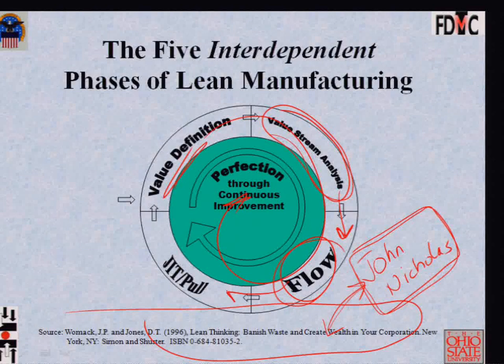After you have eliminated the flow related problems inside the value stream, then you institute pull production. You only produce to demand, and you check very carefully that you are not overproducing certain products, and you try to share your capacity, especially on the bottlenecks across multiple products, by reducing changeover times. And so there are methods like heijunka, constant work in process, or CONWIP. The idea again is that you institute pull manufacturing, you produce to the demand of the market, but only after you've improved the layout.